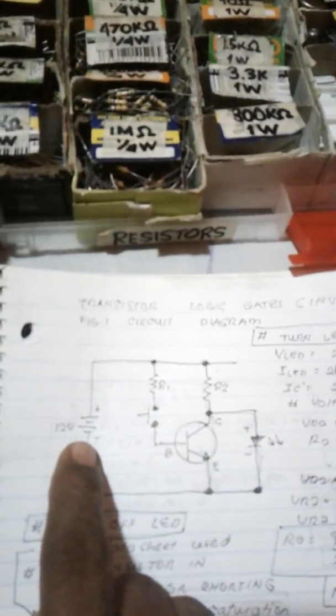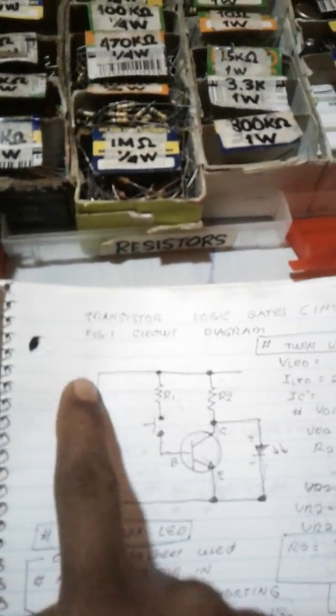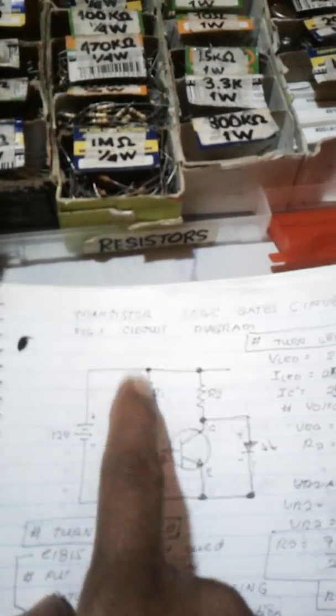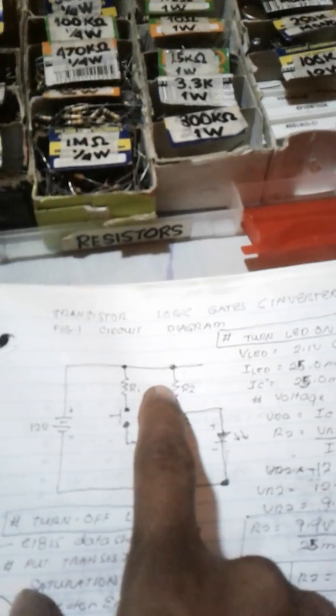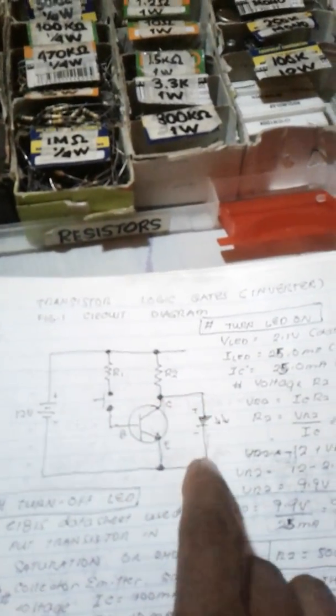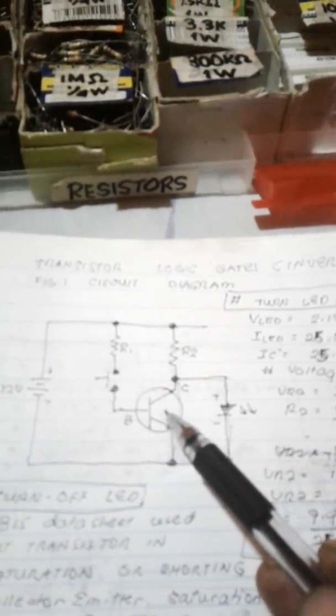using a transistor. If you push the button, it will turn off. Release the button, it turns on. Let's see the circuit. That is the circuit. We have here the power supply or the source, 12 volts. And then the resistor here, for the base resistor. And then we have a resistor here. And then the LED here. It seems that the LED is shorting this transistor.